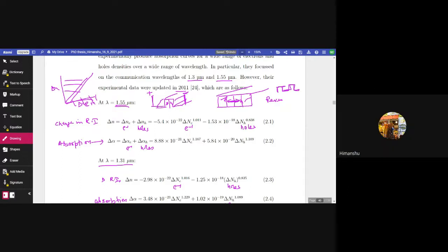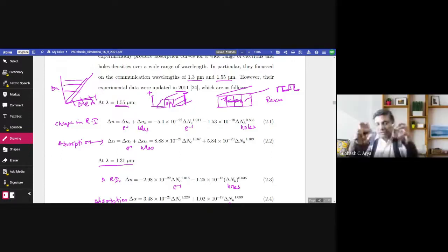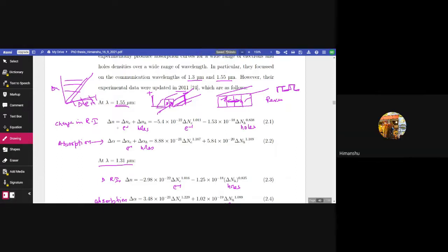So we could find a relationship between electrical phenomena and optical phenomena. Optical phenomena are being controlled by electrical phenomena: the change in the concentration of electrons and holes leads to a change in the refractive index. This is what we try to exploit. Although this value is very, very small, if we increase the length of interaction of light through the device, you can get sufficient refractive index change to achieve modulation.